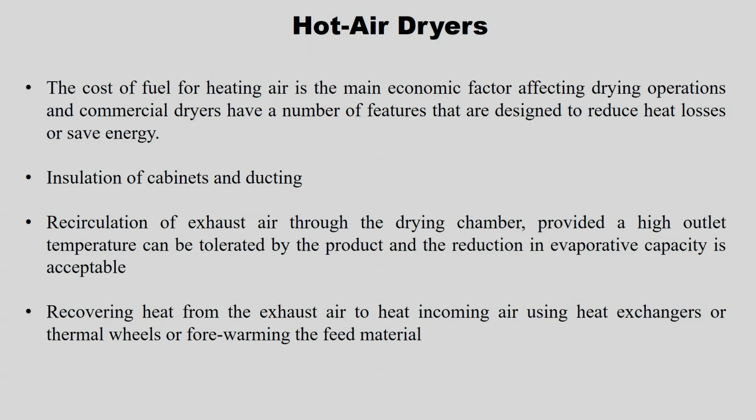So, normally the hot air dryers, this is in general. But here we are also thinking about conventional hot air dryers, and what measures can be taken to improve the process as an energy conservation process. One is insulation of cabinets and ducting, that should be done, and recirculation of exhaust air, right. So, whatever air is going out in the exhaust can be recirculated.